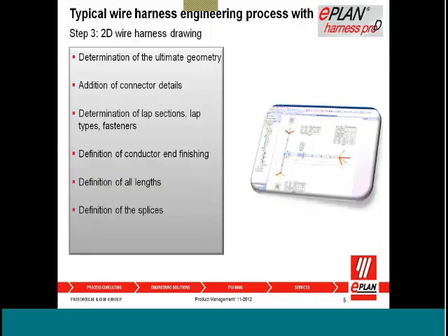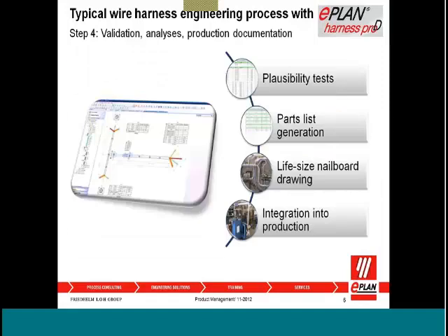Later on, we were able to then generate our 2D nail board. From the nail board we can identify our different fasteners, our lengths, our splices, and take this data out of the virtual environment into our production environment.